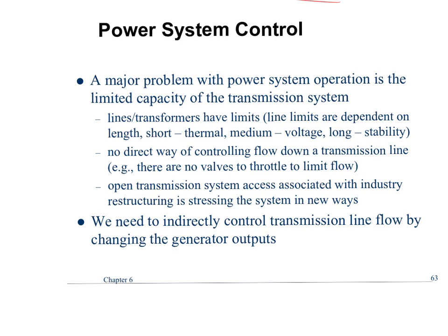It will happen automatically, because the only way you can save frequency, you can't ask generation to pick up, but you can dump load really quickly. So they'll shed load. You would never want to shed generation, because that's going to exacerbate your problem. But if your frequency drops, you'll under frequency load shed all day, every day. They'll just dump you. And I don't know who they decide dumps and how they figure that out. I've never seen that level, but you can take a look. Avangrid probably has some description on their UFLS. There's a lot of work to do that.